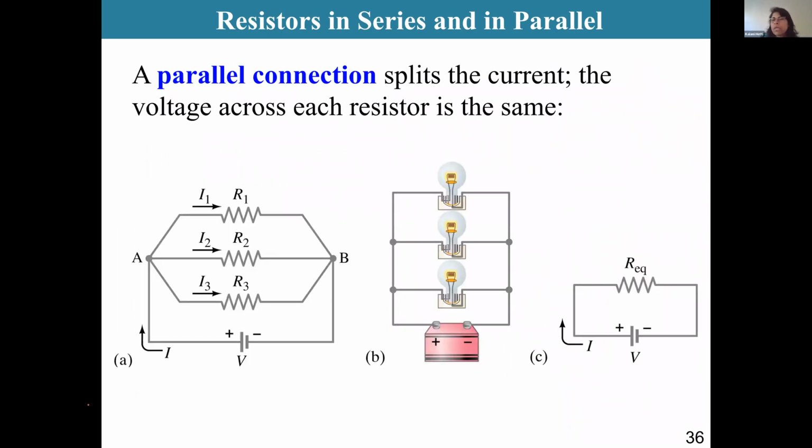But sometimes you may see parallel resistors, right? So when you have parallel resistors, here you have voltage equals I1 and R1. Here I have I2 and R2, according to Ohm's law, V. And here I have V, I3, R3. But the important thing is this voltage across the three resistors is exactly the same voltage you supply to the circuit. Then we call them parallel resistors.